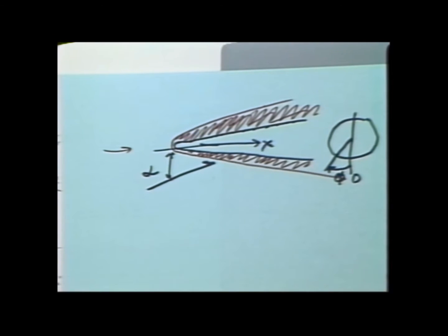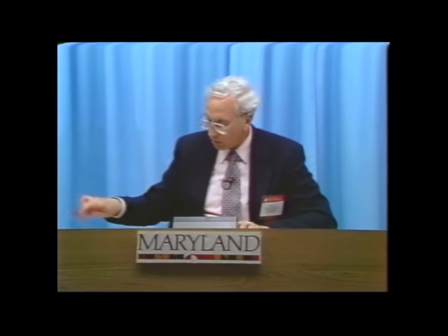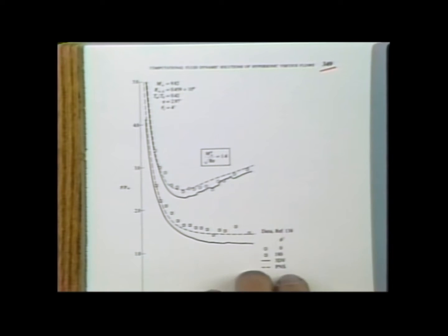And so what about viscous interactions? The effect of viscous interactions comes out in the wash automatically in this type of solution. And so the parabolized Navier-Stokes equations are calculating in a reasonably proper way the viscous interactions. And we see that there's a big difference here. This big difference translates into a particularly big difference in the axial force coefficient.